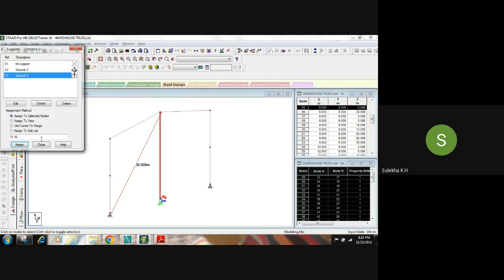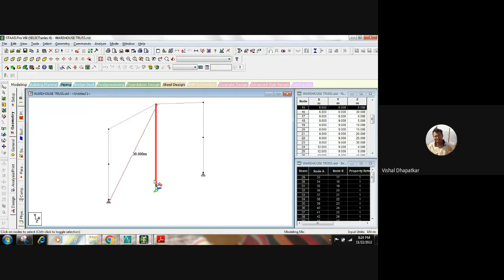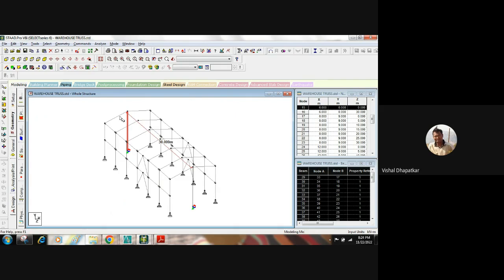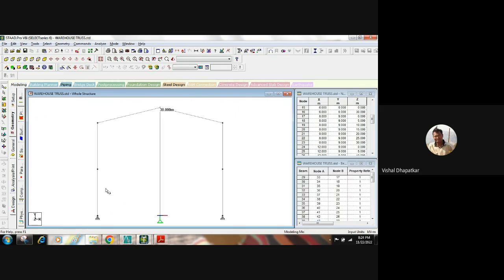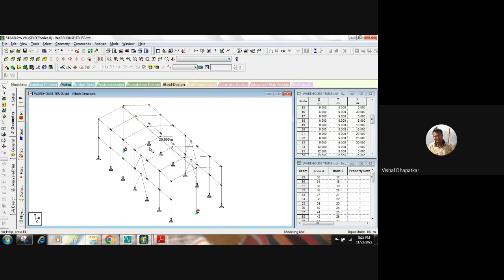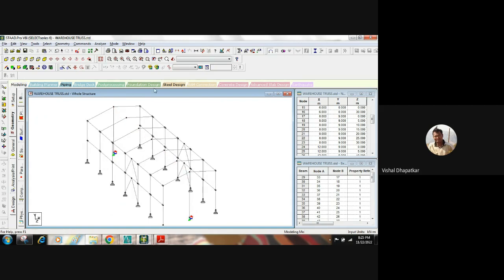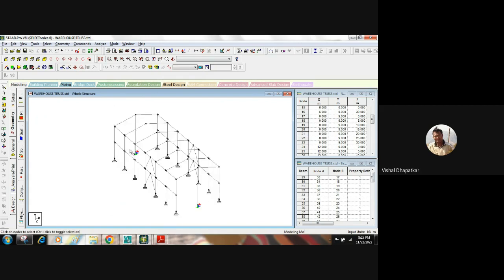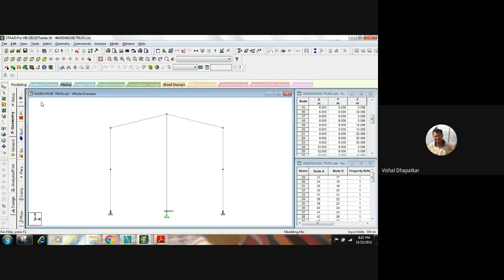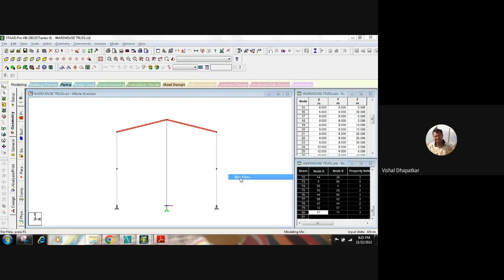Okay, sir. Practically, how can we do that at the site? You have to arrange the bolt arrangement. You have to prepare it such that the bolts will take some fixity or some movement. So it depends on the arrangement of the bolts. Do you know how we can achieve the pin and fixed connection in steel structure? Let's discuss that later. While designing the base plate, we'll see what a fixed type of connection is and what a pin type of connection is.